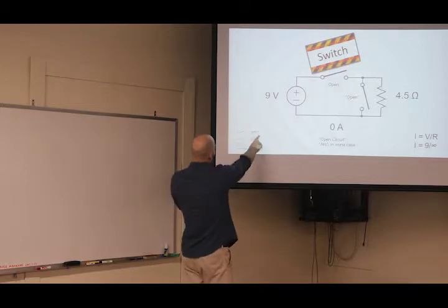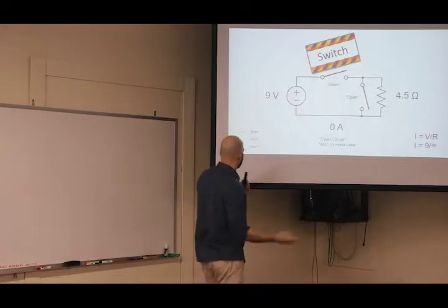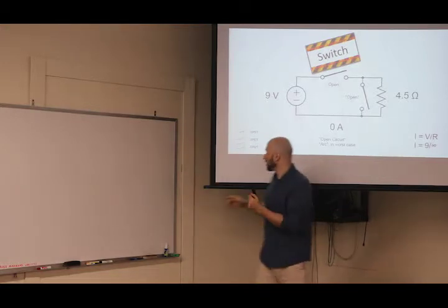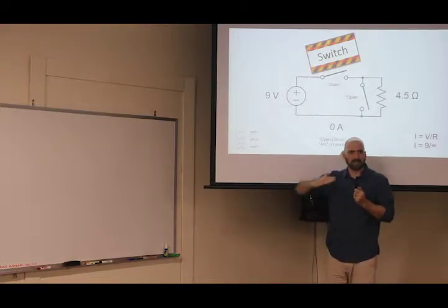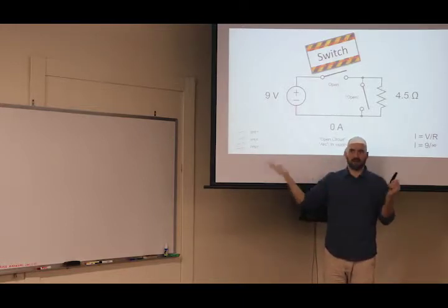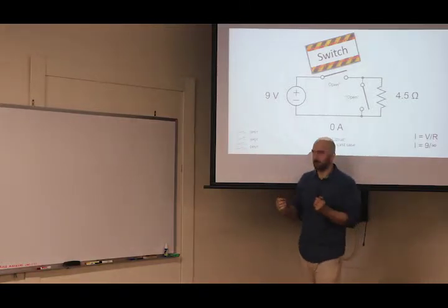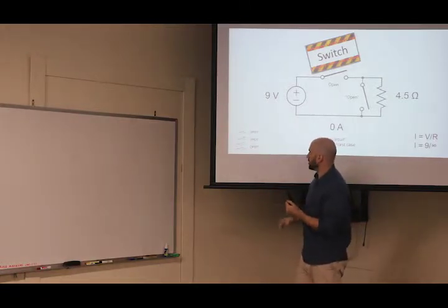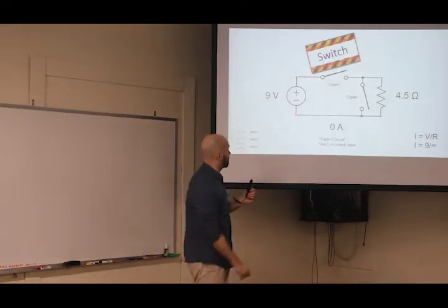If you see stuff like this, S's, P's, T's, D's, and 3's, you don't have to memorize all those. I put them very tiny because it's not that important at this point, but this sort of code is for the different number of poles and throws. It's like a different configuration of contacts. So maybe instead of just opening the circuit and not letting any charge pass through, you're going to move it from here to here, and now the charge will pass through this way, kind of like a valve in a fluid system. That's what those are. If you see one of those in a switch, or you know what switch you want, just use those codes to figure out what you need to buy, or what the other person's talking about.